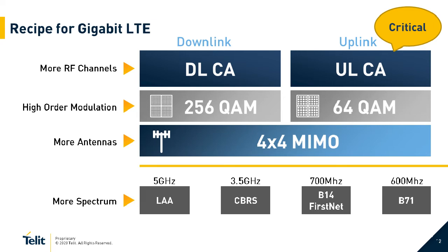This is the Wi-Fi spectrum band, and as you may or may not know, the Wi-Fi operates in spectrum which is basically free. There is no license, but you have to follow certain rules to make sure that you don't interfere with other users. And so with LAA technology, cellular LTE modems are also able to operate in this frequency and do carrier aggregation, and basically use LAA frequency as an extra lane that they can add into their highway.